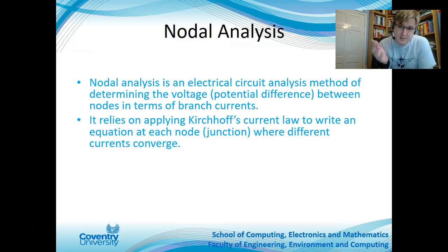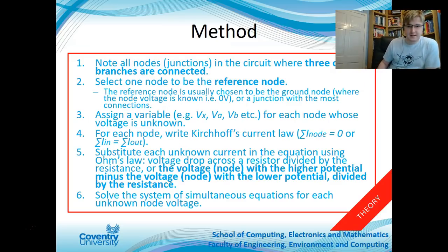Remember how in mesh analysis you're looking at the loops and using Kirchhoff's voltage law to find the voltage drops in a loop, and the voltage supplied by the loop. That was all using the voltage law. Nodal analysis is just using the current law instead. So let's get on with it. Okay, this is important to know.